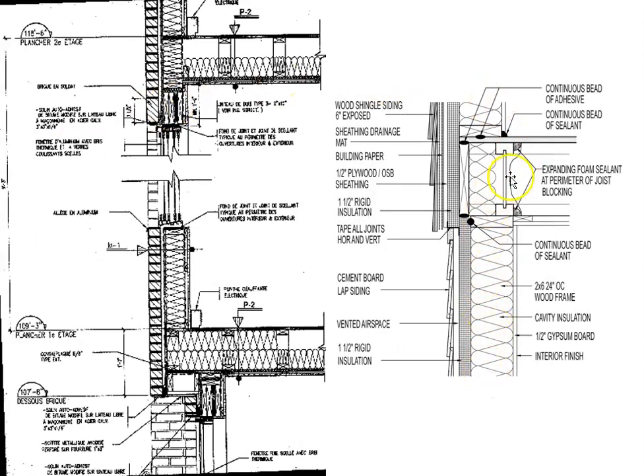So here's the I-joist cut in section. Here's a rim board. You typically would not put I-joists at the end because they don't provide good nailing surfaces for what's coming on the outside.